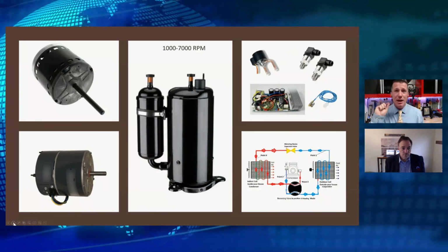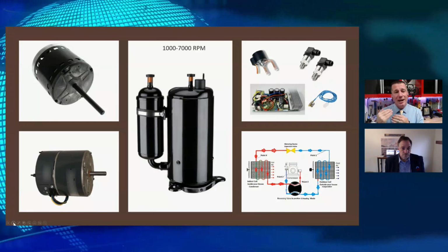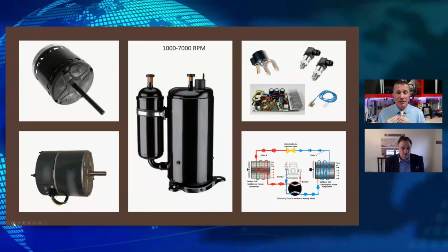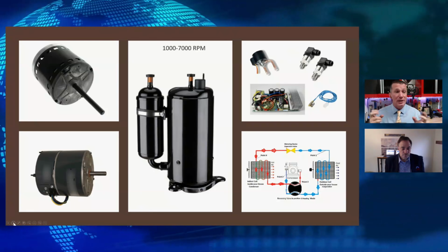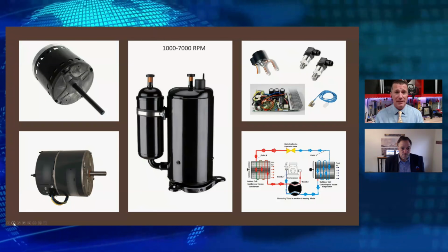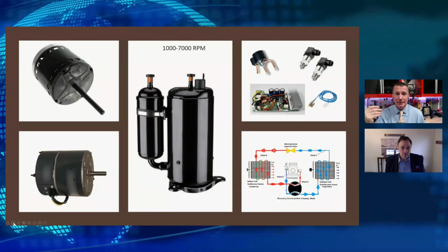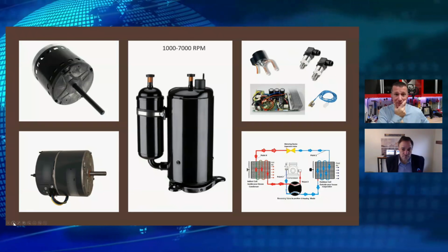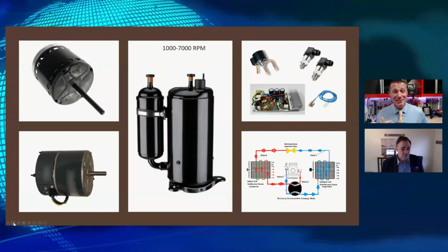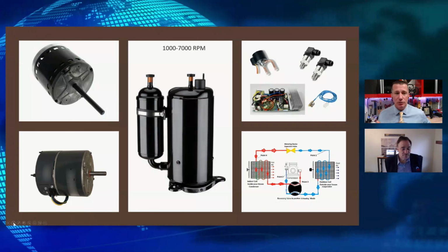And if we look at the RPM ranges on these motors, they're getting so high now, we can overdrive our compressors. So we have things like boost mode and hyper mode where we're adding significant increases of RPMs onto the motor past its design point. Anyone ever heard of that? Got quite a few people out there in the audience, and I hope I'm not diving too deep into this because this is a really interesting perspective on how we're producing heat in these ultra low temperatures.